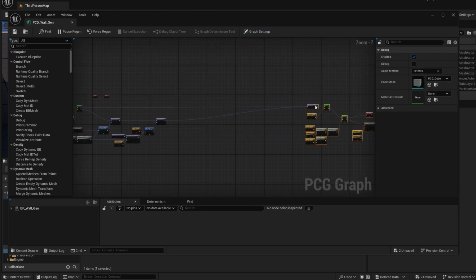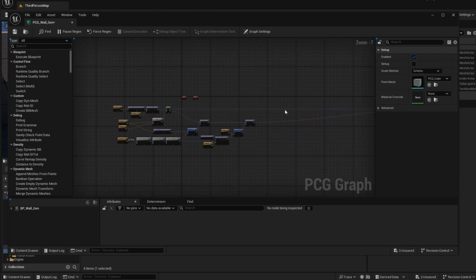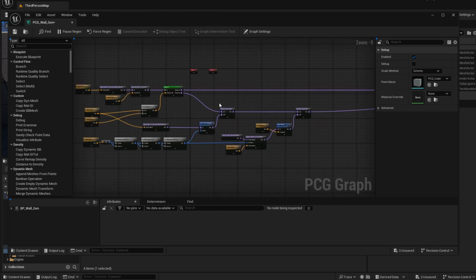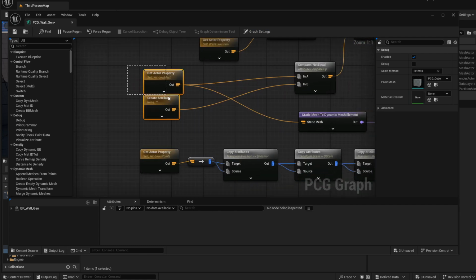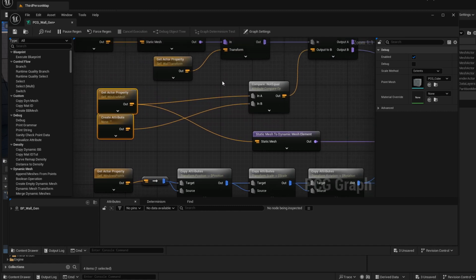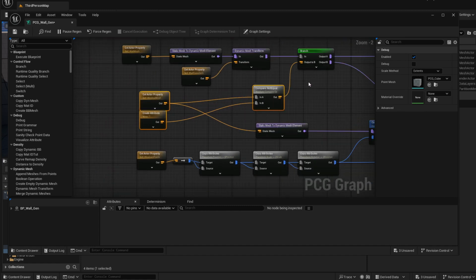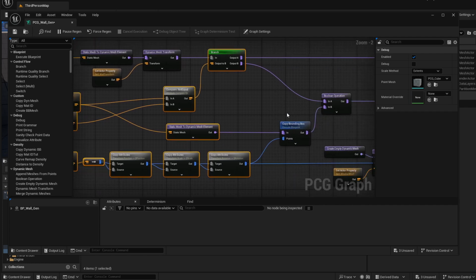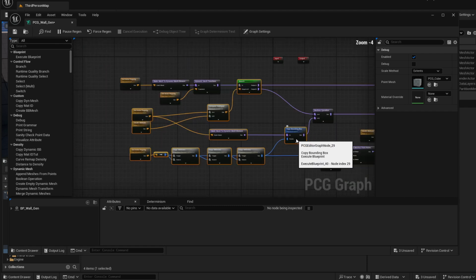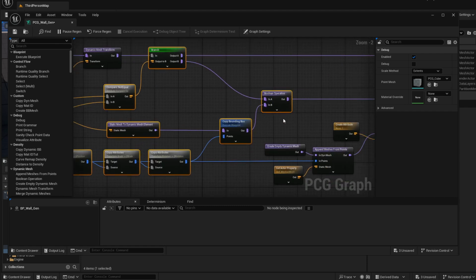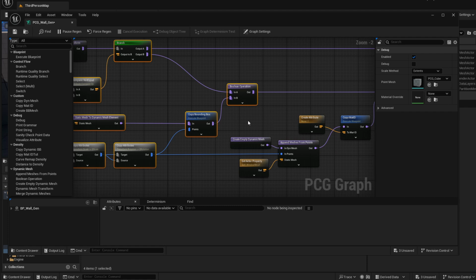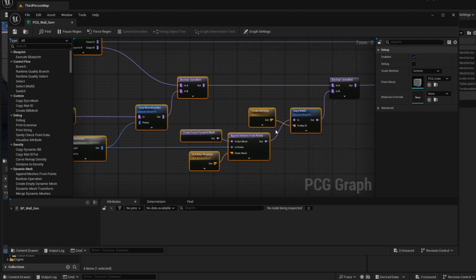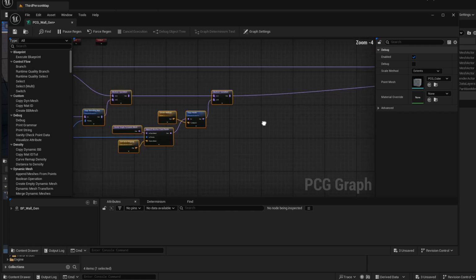And let's move everything here to the end. So for the windows, we are getting the mesh, checking if it's valid, so it's not an empty string. We are then copying the points attributes to the actual points position, rotation, and scale. Then we are copying the bounding box, cutting inside the wall, and then applying the mesh with a union.